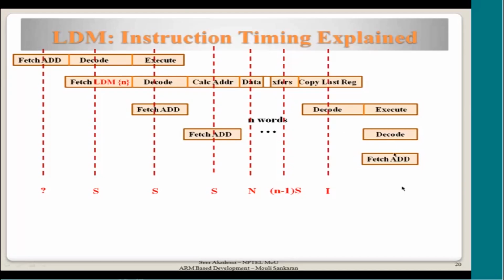Okay, and then this will be, again, be careful. Don't look at the fetch and then say it will be an S cycle. It will be an N cycle because it is something different from what the previous access was. It was to do memory. It was to do some data address, and this is some instruction address which is non-sequential. To start with, it will be non-sequential. Now tell me how much time it has taken.